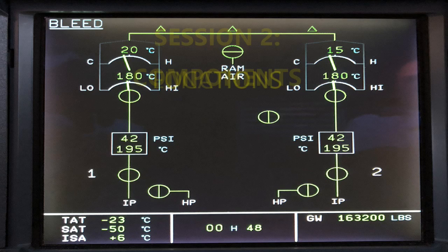Okay, all right, so then the fan air valve. There's a fan air valve. It is downstream of the Precooler exchanger, and its purpose is to basically regulate the temperature of the air. Okay, so that's what it's doing.